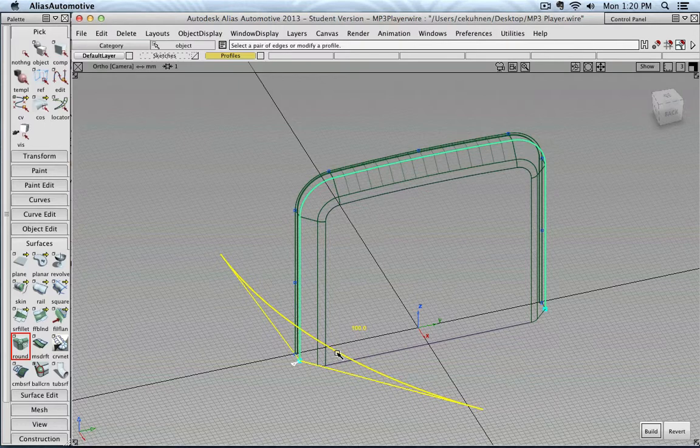To change it, you can, for example, click this part of that widget and then drag your mouse. And once you have it selected or you clicked once on it, you see it's white. That also means you can put in, for example, the radius by just simply typing 2 on your keyboard and pressing enter.